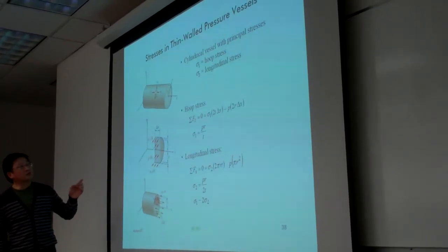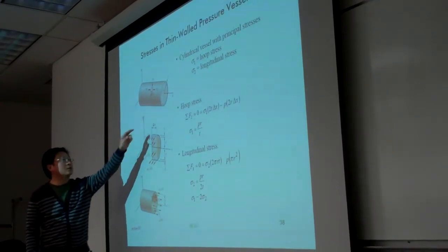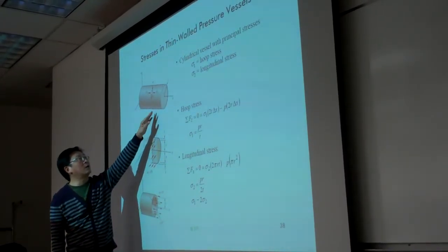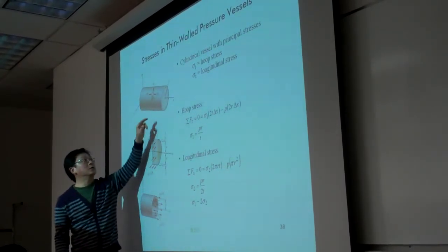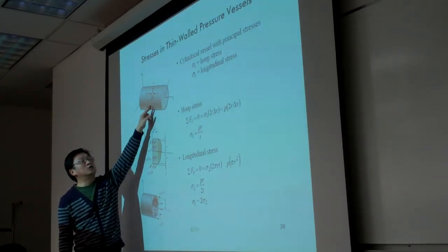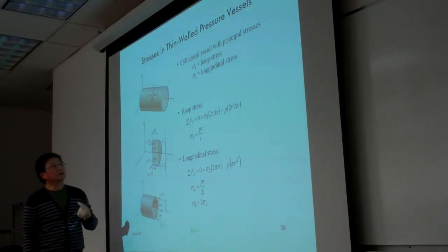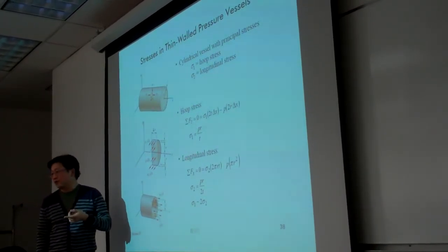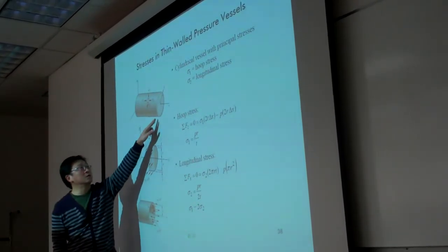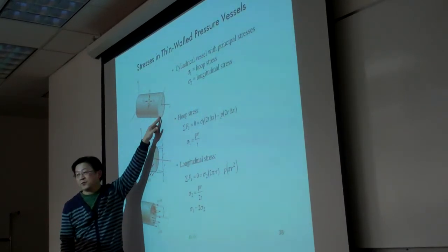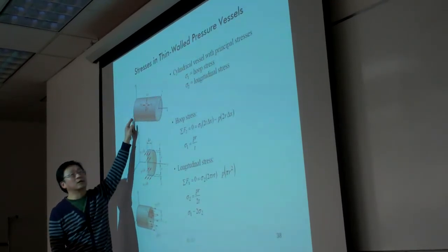And so for pressure vessels, what we like to know is, given the size and the thickness of the vessel, we want to calculate the stress imposed by the internal pressure on the sheet of the tank. If you wish, you can write this up in your notes: one assumption is that the thickness is small compared to the diameter or the length.